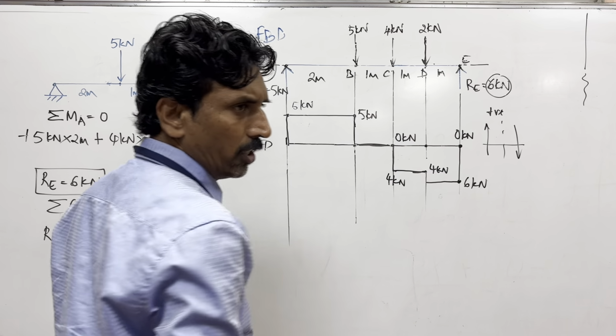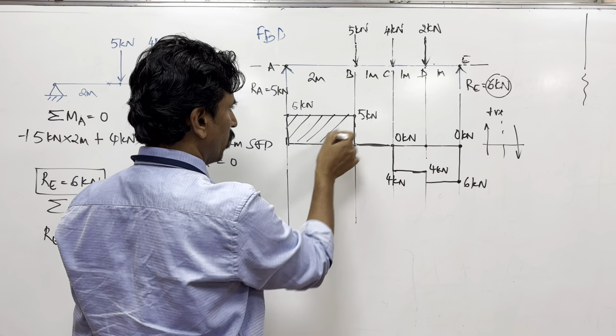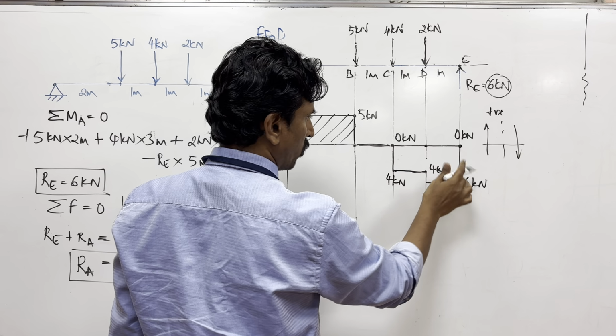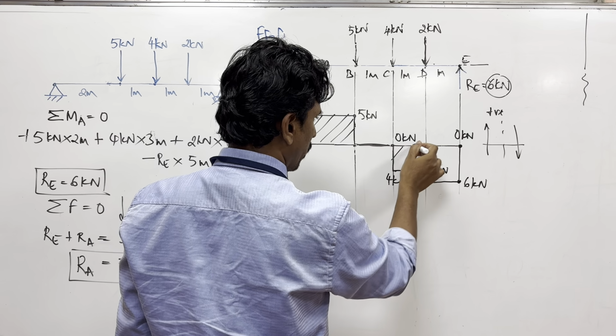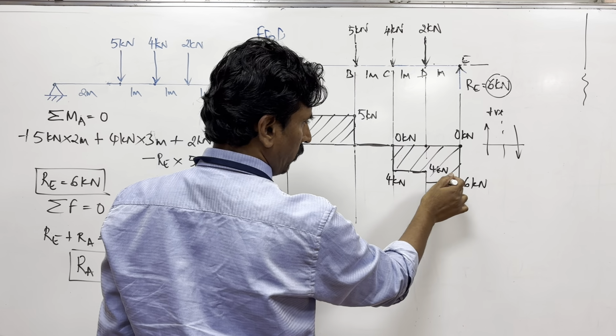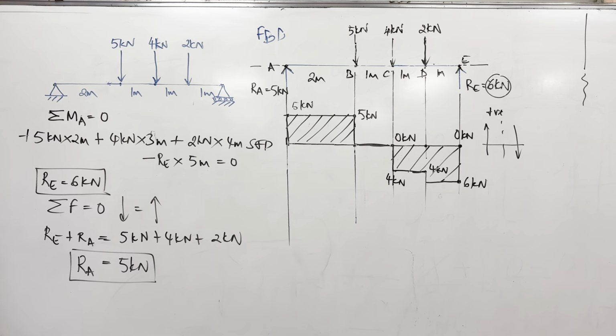And it is the variation here. You see that the variation is like this, which means that you have got the 5 kilonewton shear force here, 6 kilonewton shear force here, and at some point it is 0 kilonewton here. So there are no shear forces acting at this point, and here you will see the highest amount of shear force.